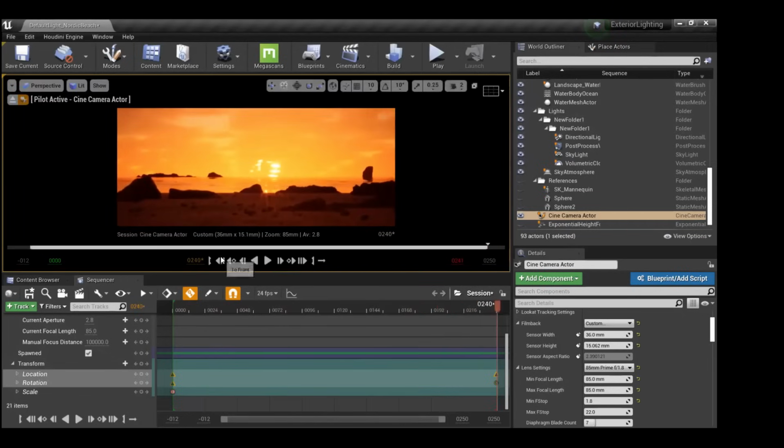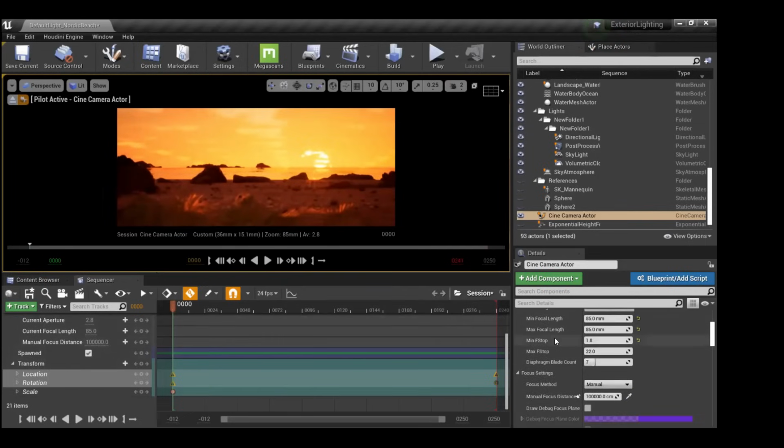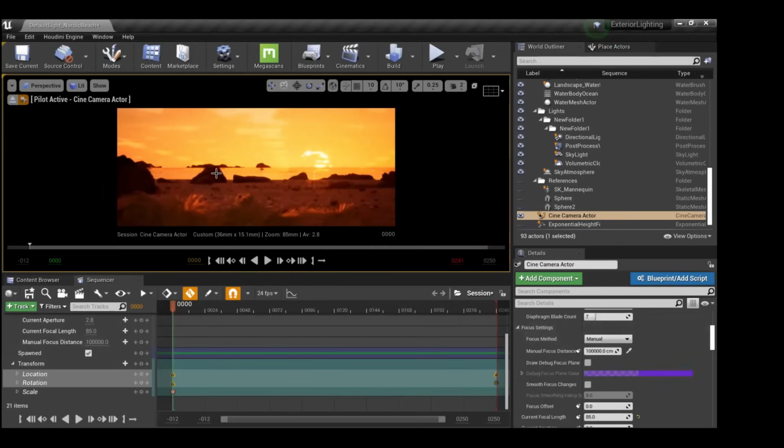But what I want now is to add depth of field in here, right? I want the focus to start from here and end at that island which is far away. I can do that also. Now there are two options. You can do that manually, or you can track the camera. If you want your focus to remain on this object, you can do a tracking thing. Like the tracking thing which I did in the starfish chain, I just click that starfish and it will keep the focus on that starfish only, right? And we can do this here. I will just go to manual. You can preview how your focus is going. Basically just click on the object first, right?